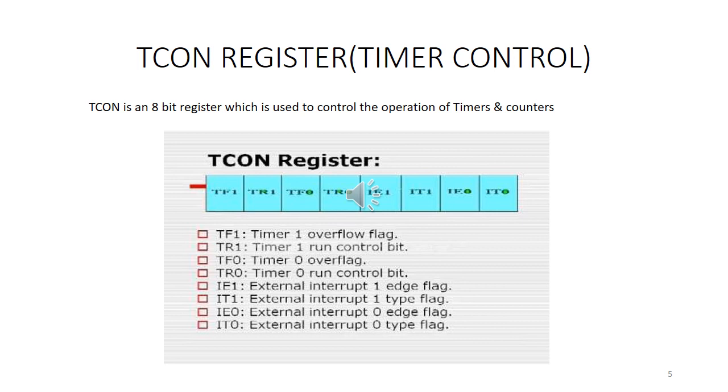This bit is used to start the timer along with stopping the timer by using the SETB TR0 instruction and the CLR TR0 instruction.